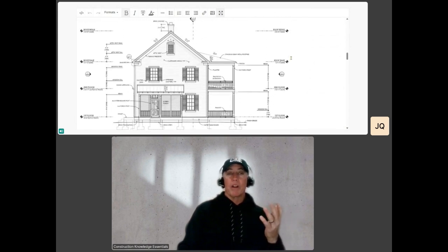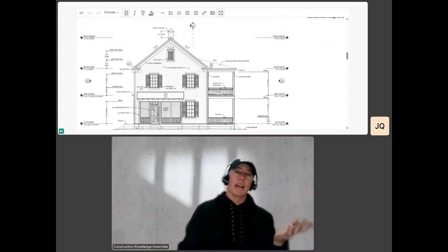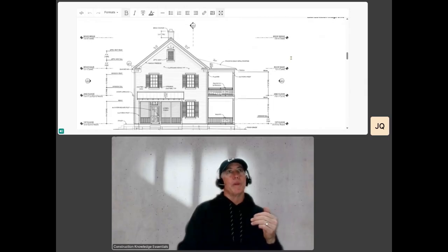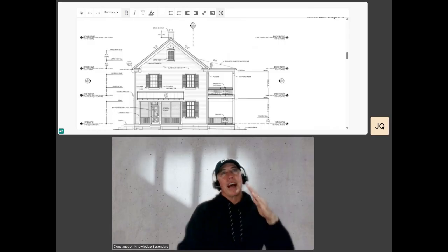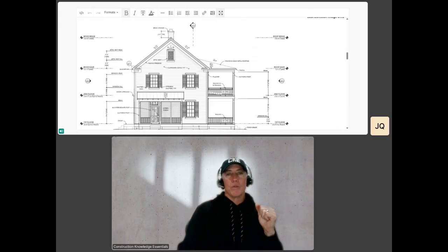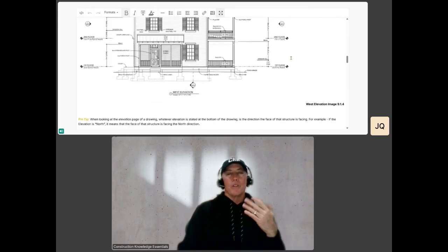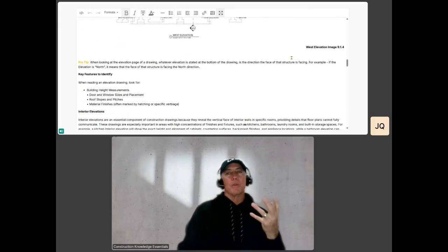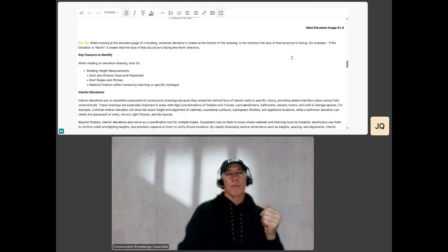Certain areas are heavier, more for snow because you want that dead load off of your roof. And if you were to be more south, your pitches are not as sharp. They're eased a bit because there's no need to run off the same way. So all of those things are taken into account when you're working your way through a set of plans.